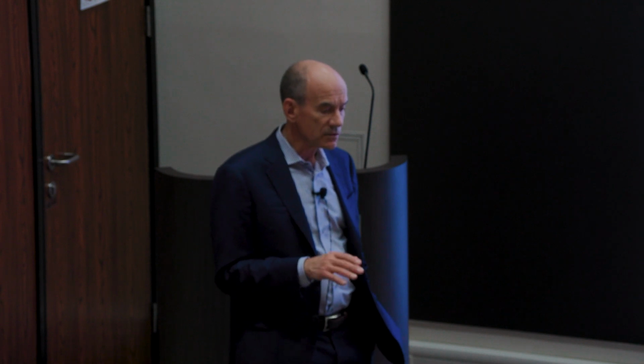So, I don't know of a study where anybody has looked at what density of cracking you could tolerate, but it's not going to be high. And I don't think it's a strategy that you can use and say, well, you can tolerate a certain number of cracks. I mean, coming back to the tandems, that's another argument I heard that's sort of related to this. People say, well, okay, it's a tandem. If the perovskite cell degrades, so what? You're left with the silicon cell. Well, you can't have a degraded perovskite cell sitting in an encapsulated silicon module. It's going to cause all sorts of troubles.